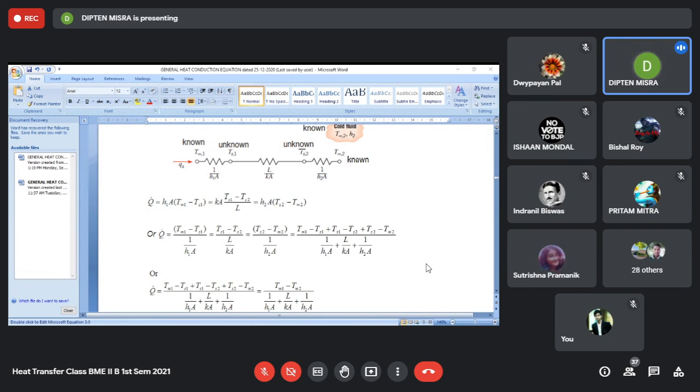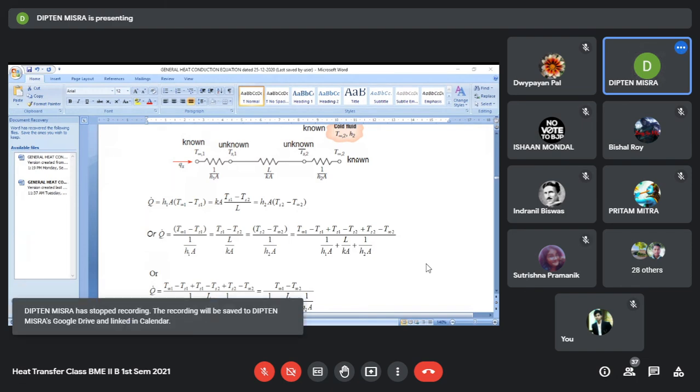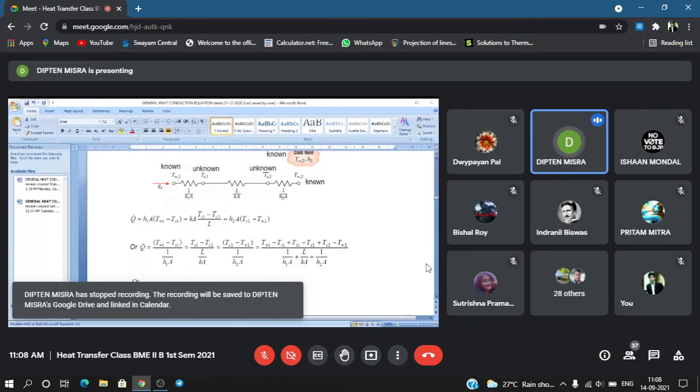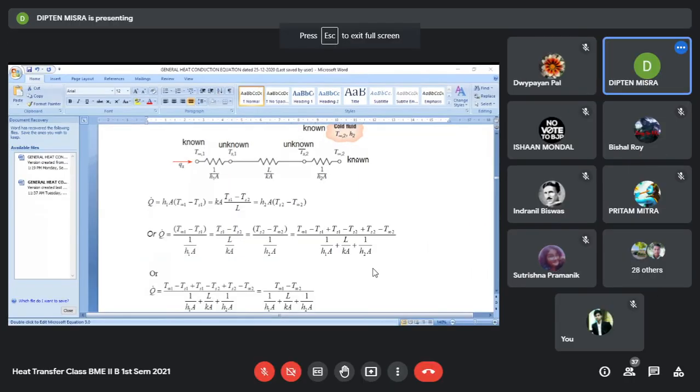Sir, please tell me, can you repeat why it is T infinity? Infinity here does not mean the temperature is infinity. T infinity means the temperature at a sufficient distance away from the wall, where there is no change of temperature.